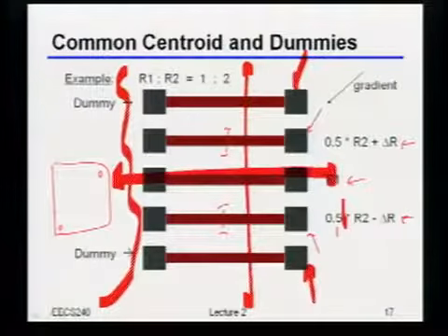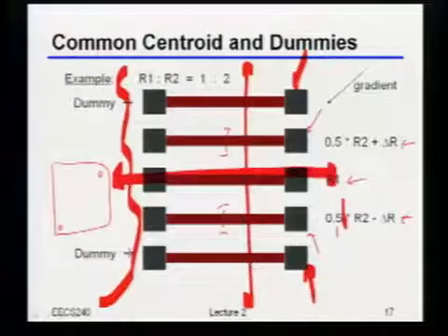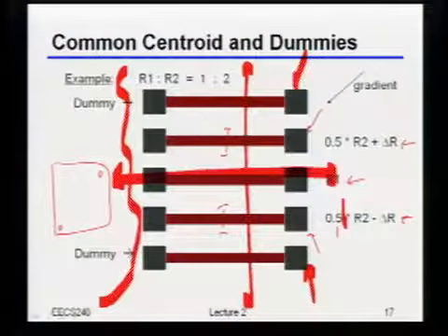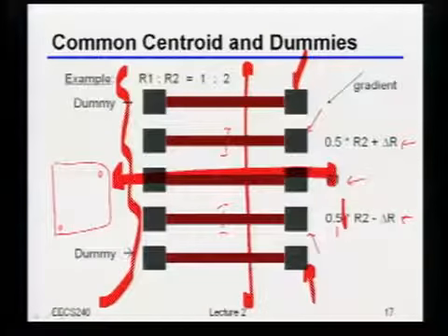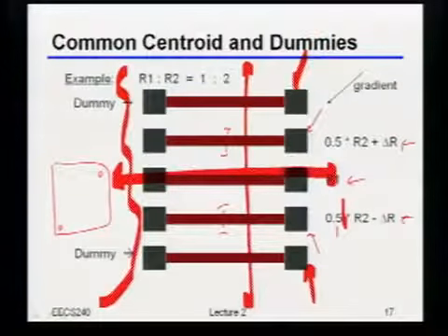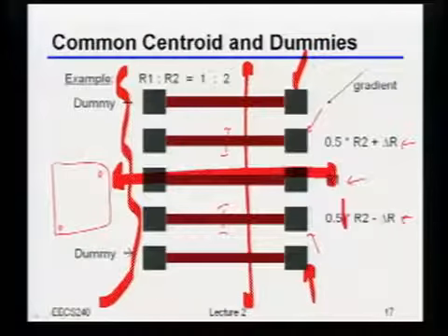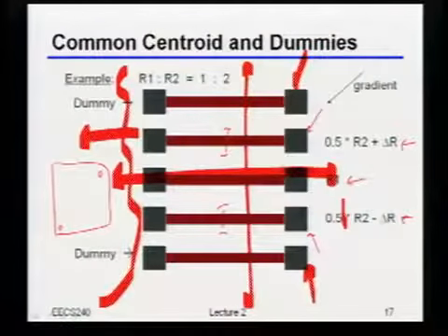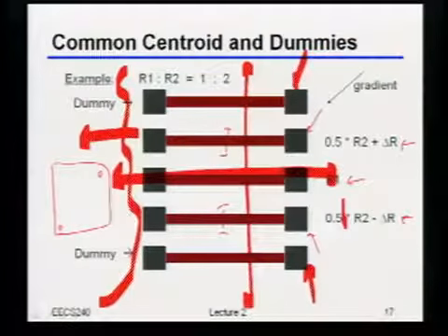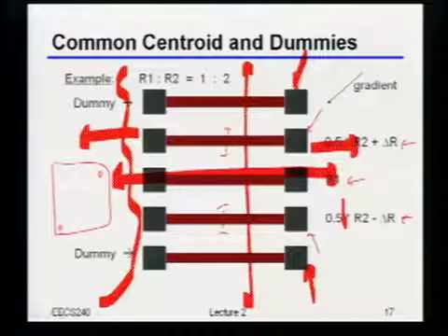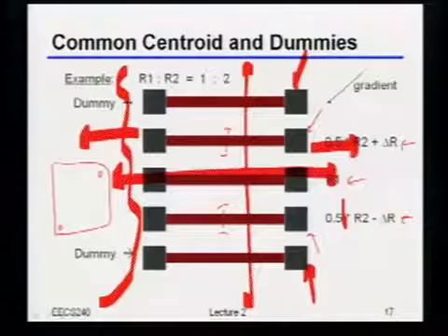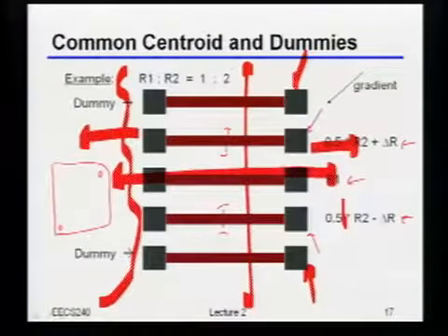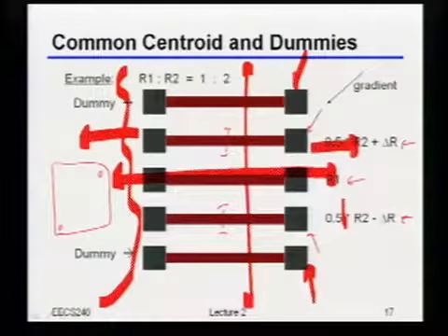One example is that people are now actually mechanically straining the transistors. They put these capping layers that literally are either stretching or compressing the channel. Well, guess what? It's a mechanical thing. So if there happens to be some other capping layer not that far away on one side, and no capping layer on the other side, you get a different stress, and therefore you get different characteristics. So bottom line, if you care about it, just make it the same.